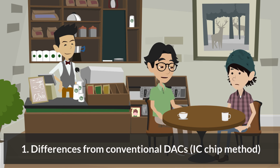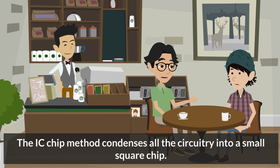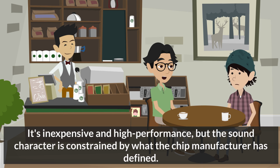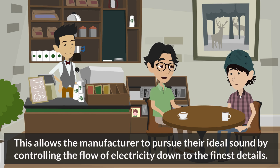First, differences from conventional DACs, the IC chip method. Most audio equipment uses DAC chips, ICs, manufactured by companies like ESS or Asahi Kasei mounted on a board. The IC chip method condenses all the circuitry into a small square chip. It's inexpensive and high performance, but the sound character is constrained by what the chip manufacturer has defined. In contrast, the discrete method builds the circuit by arranging dozens to hundreds of small components on a board. This allows the manufacturer to pursue their ideal sound by controlling the flow of electricity down to the finest details.